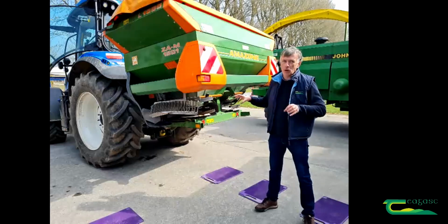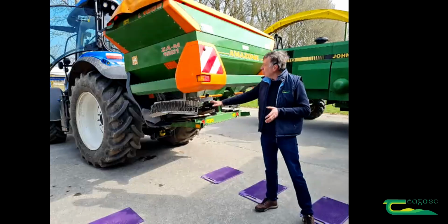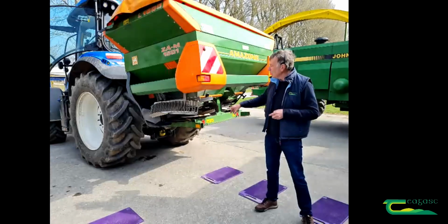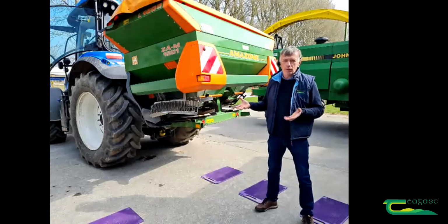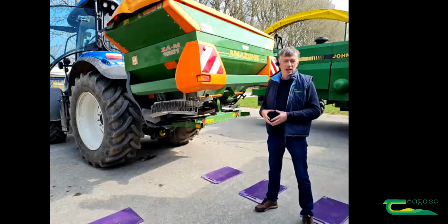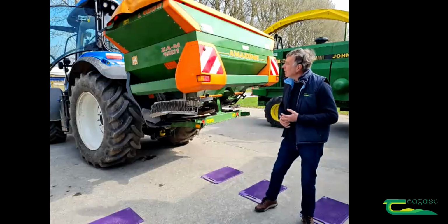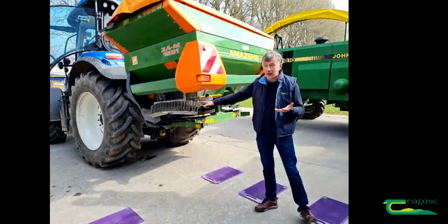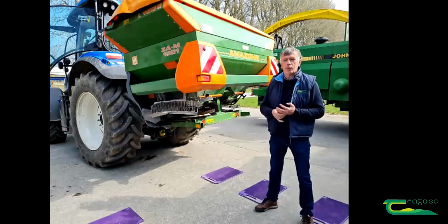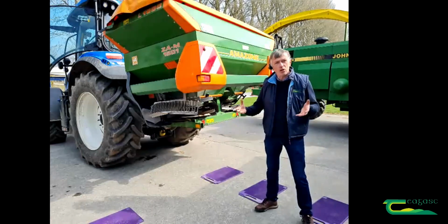What's really important is that those are set correctly for the spreader. And when you're purchasing a spreader, I think you would want to give a good bit of thought to the headland management system on it. Because remember that even in something like a 6 hectare or 15 acre field with a 24-meter wide spreader, something between 20 and 30% of the area of that field is going to be on the headland. So if we're not getting that right, it's going to be a big loss. So that's hugely important. Another aspect of headland spreading is getting the right position for turning on the spreader when you're leaving the headland, and turning it off coming off, getting that correct. And that's where GPS comes to help us.